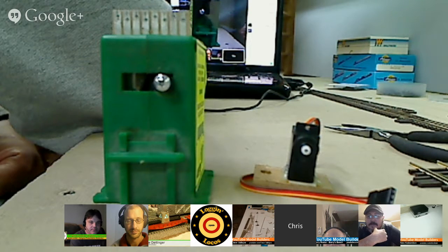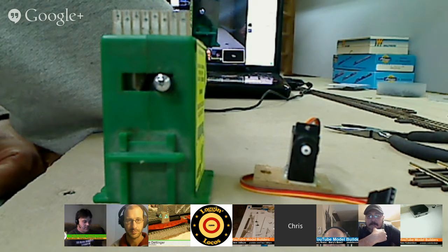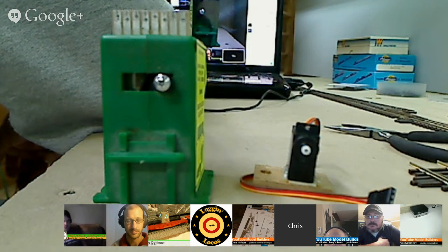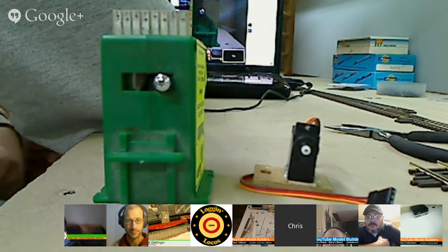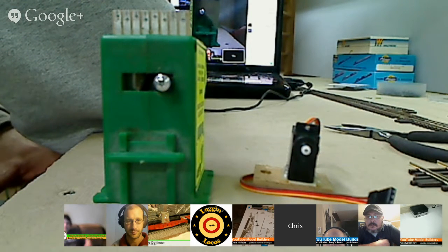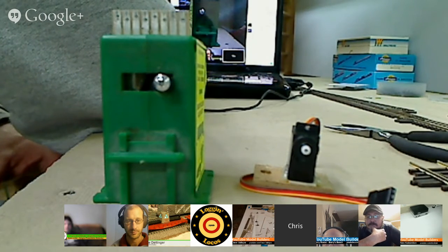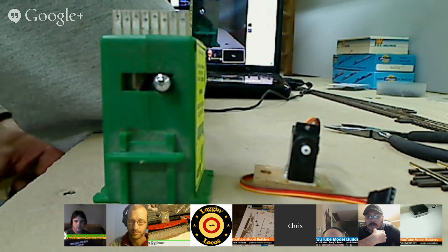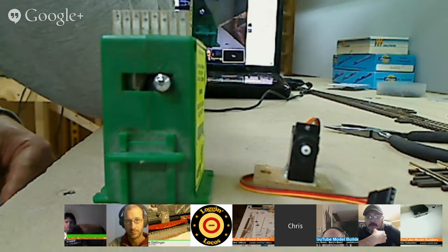The servo comes out of the wood bracket, and then you take the horn off it, put it on a new servo, stick it back under your layout, bolt it in place, and then you can re-gear the servo that you just took out. And even Chris here, he's got 1 screw. He pulls that little plate off. That was probably a pretty smart idea. You can adjust it with a little bit of angle left or right.